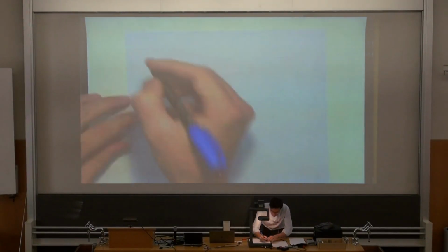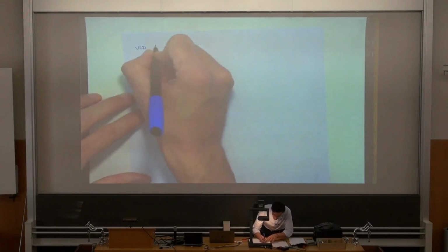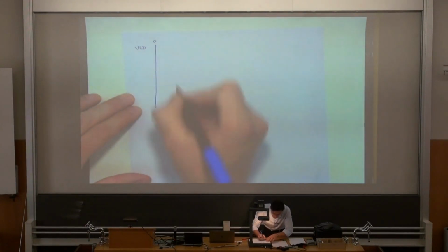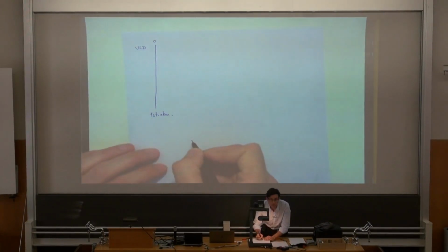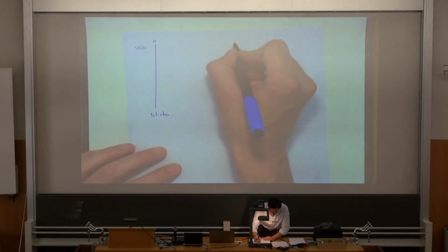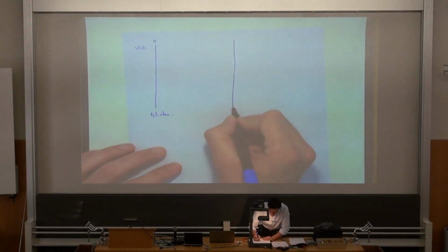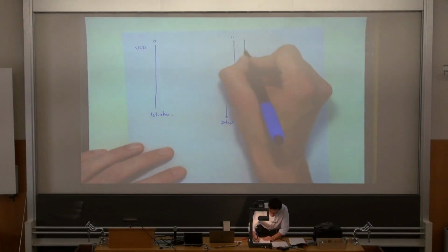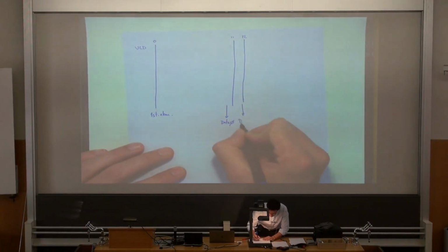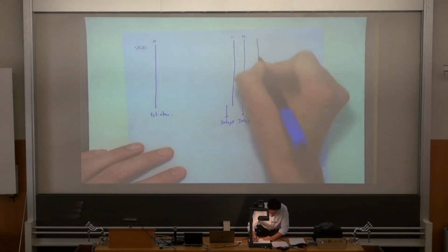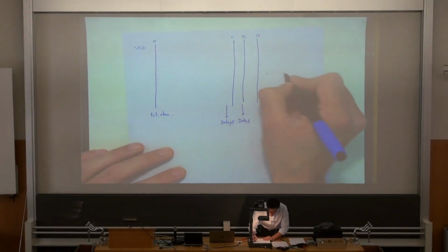So for example, for the vector load, in cycle 0 we start the access to the first element. After 11 cycles we will have data element 0. Then, one cycle later, in cycle 12, we have data element 1. In cycle 13, data element 2, and so on.